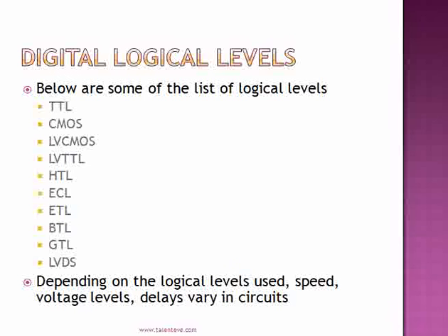If we see in embedded systems, there are several digital logic levels depending on the voltage level. So this is a small list of logic levels. Most of the embedded engineers work with TTL, CMOS, but if we go further to high-speed designs, we might have ECL, HTL, and then LV CMOS, LV TTL, the low voltage CMOS, low voltage TTL.